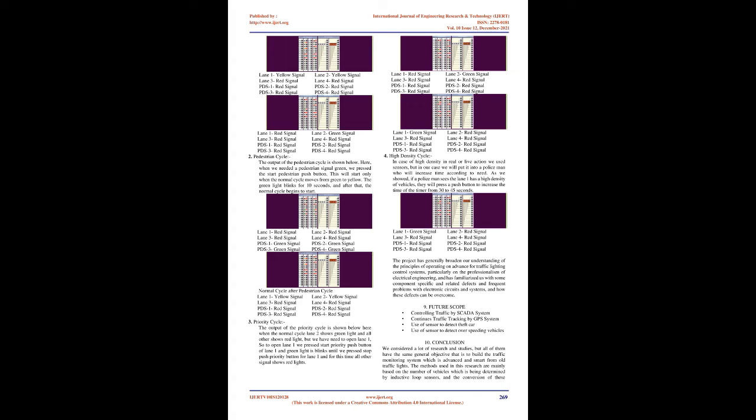7.1 Implementation. There are several ways to do our program of the advanced traffic signal monitoring system, i.e., ladder logic method, sequential output method, etc. We use the ladder logic method in our system. In our program we use input push buttons, output, binary, MOV and timer. A timer is used to glow the set of sequence accordingly in time. The program is reset using the end timer to continue running. MOV is used to extend the timer time. Binary is used for latching.